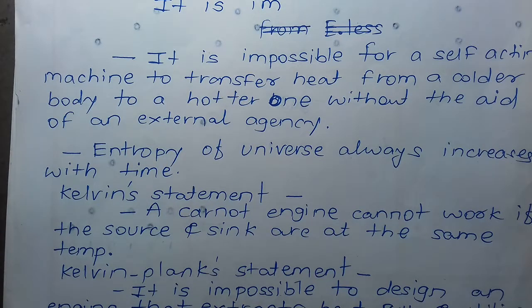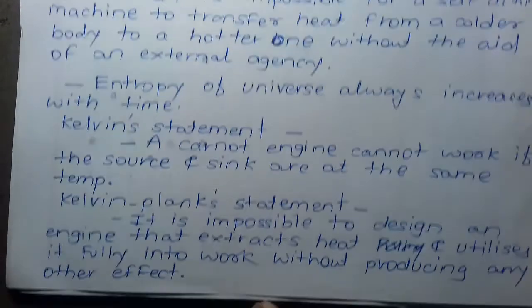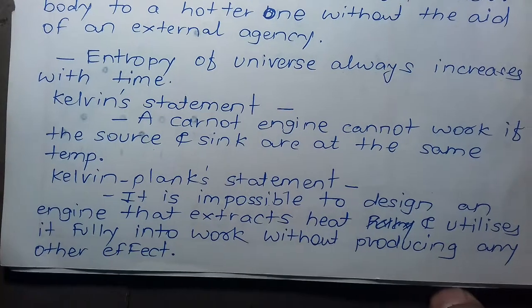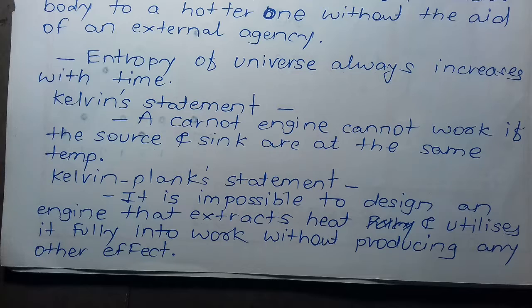Entropy of the universe always increases with time. Then Kelvin's statement. A Carnot engine cannot work if the source and sink are at same temperature. Then Kelvin Planck's statement. It is impossible to design an engine that extracts heat and utilizes it fully into work without producing any other effect.